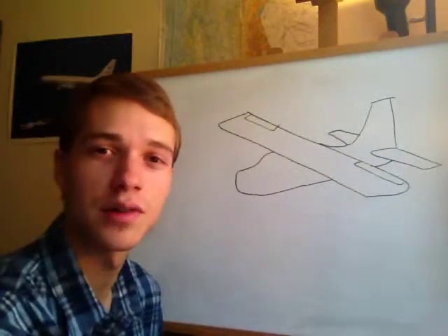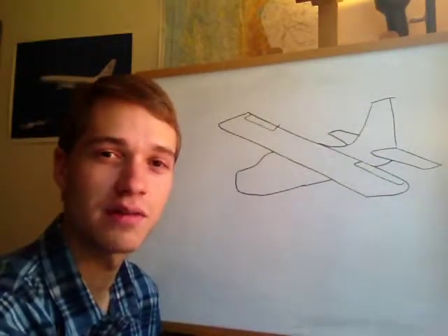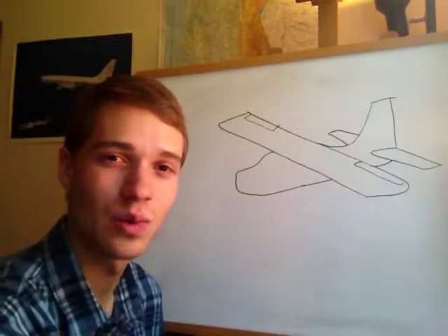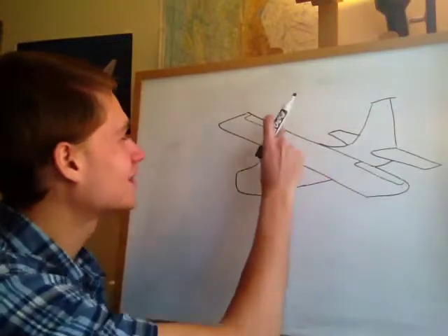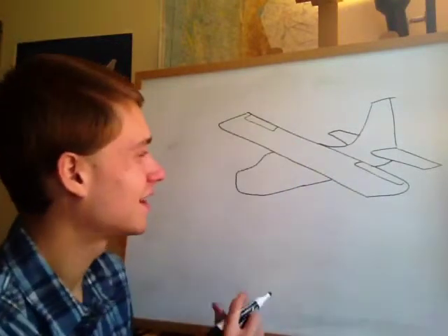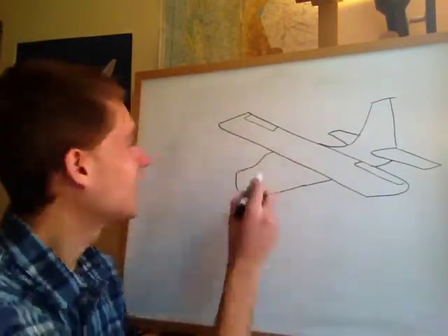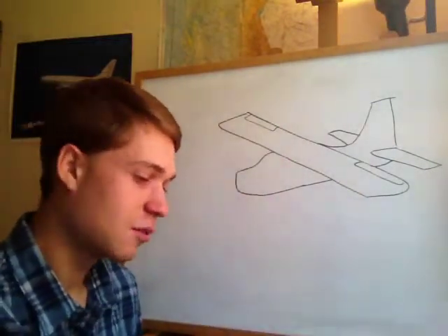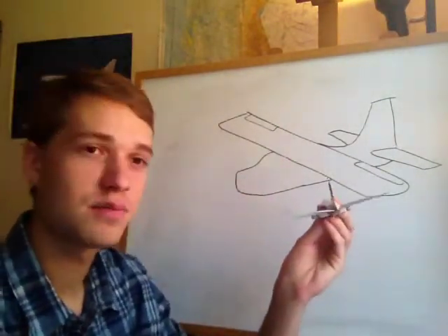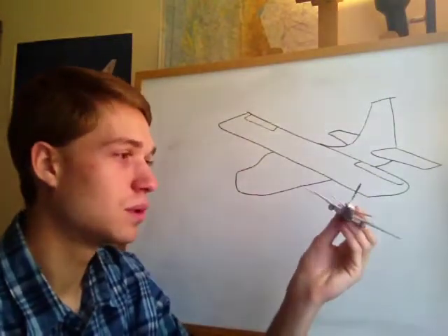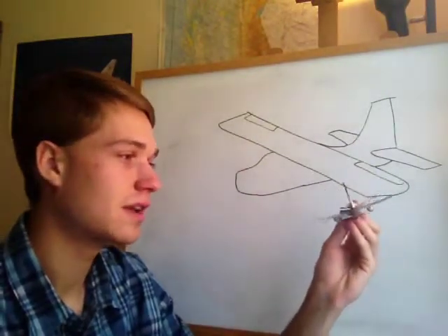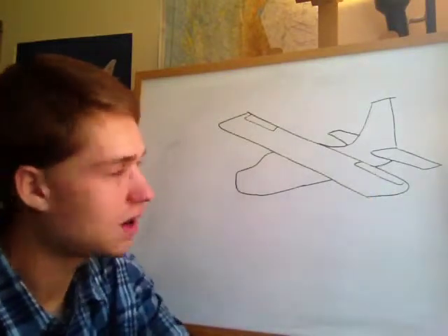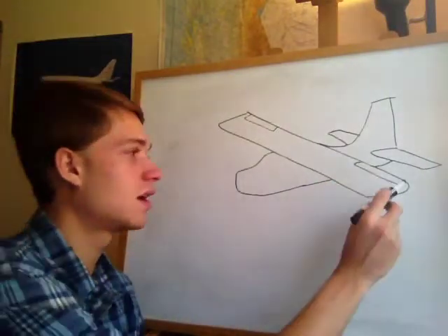These were called ailerons. And I looked up the word. It is definitely from the French. And I guess it meant something like little wings. So we have these little wings on the large wings, and they are hinged surfaces. So when you deflect the ailerons, that's how you bank an airplane. So you maneuver the airplane on its longitudinal axis by rolling it using the ailerons. All right, so that's the ailerons there.